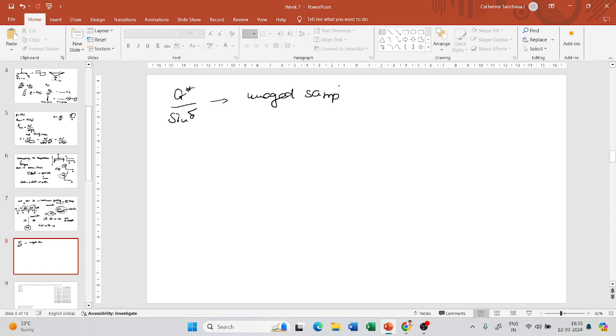In order to find out the high temperature PG, you will test the bitumen in a dynamic shear rheometer with sample dimensions of 25 mm diameter and 1 mm height, right?